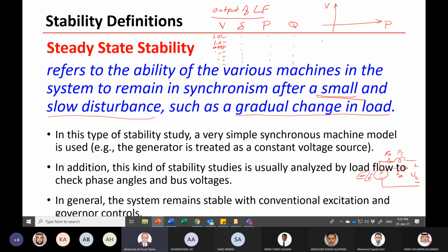Is it clear? Yes. So maybe the voltage is not reducing as much, but the voltage could be going as such. Although the voltage here is very close to 1, you are also very close to instability. In general, the voltage profile doesn't reflect the voltage stability.